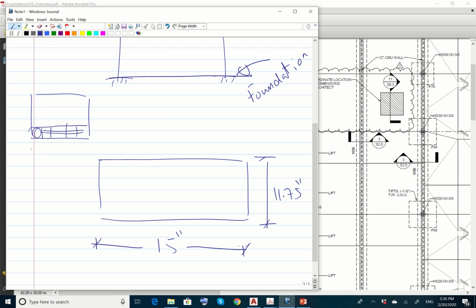The total width of that paper was 11 inches and the height was 8.5. So if you use this layout to plot your view or your plan, it's not going to fit the drawing with the scale that we mentioned, 1/8 of an inch equal 1 foot.